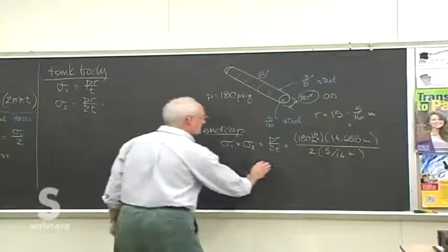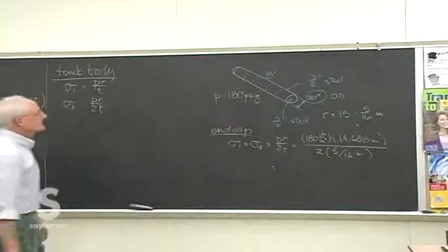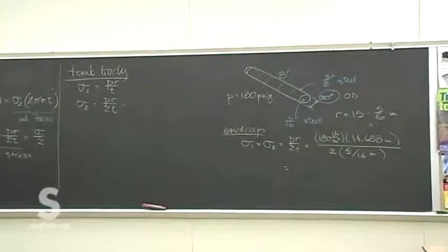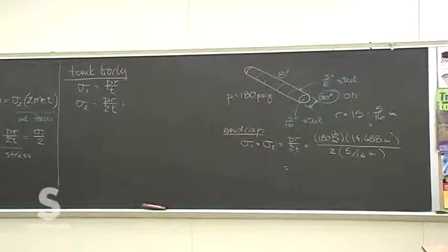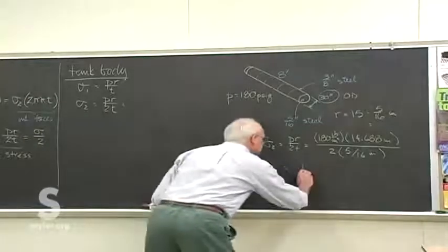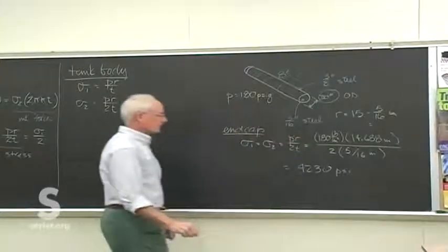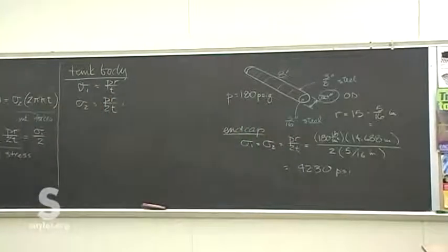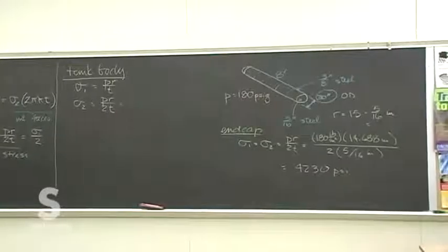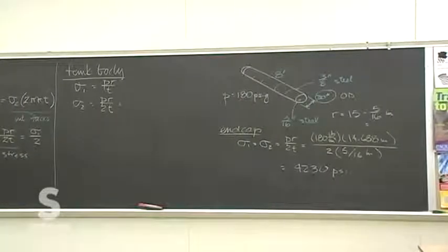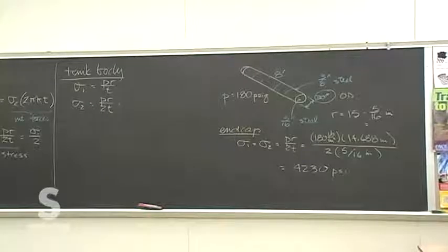And then the same kind of thing, same pressure, slightly different R and T on the tank body calculations. Now that is not PSIG because these are not fluid pressures, these are stresses that we're calculating here. There's no such thing as a gauge stress, not that I know of. Bill, you got that number?